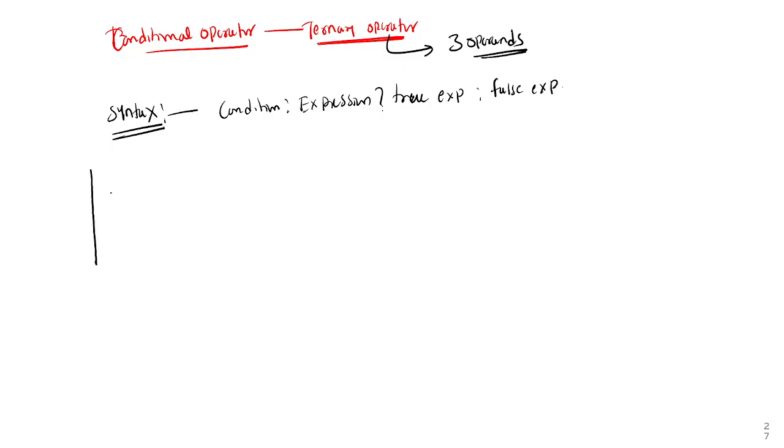This is mainly used in digital. We can write it by the ternary operator. In digital, you have already seen 2 cross 1 mux, no? You can write the logic in one line with the ternary operator. It is like an if else statement only. Let us take the inputs as a and b, the selection line as s, and the output as y. For this I am writing the ternary operator.